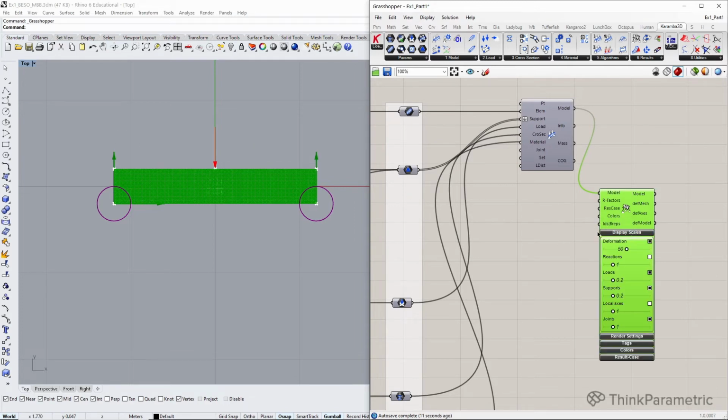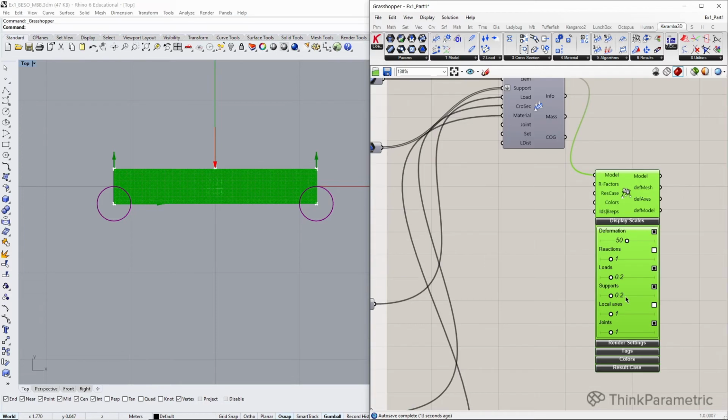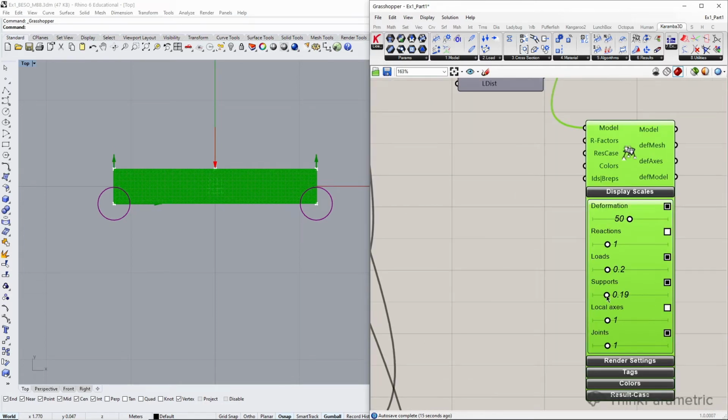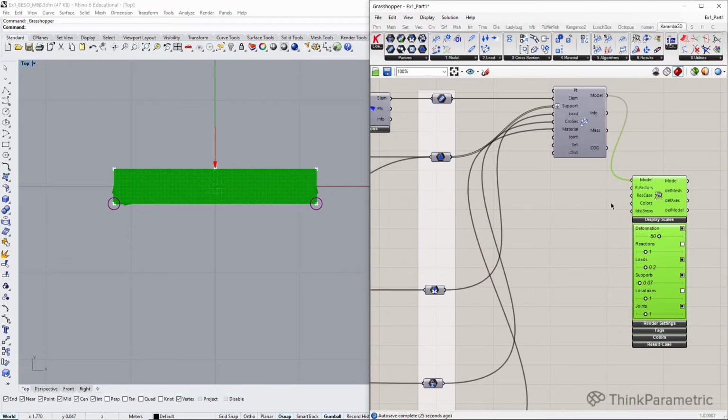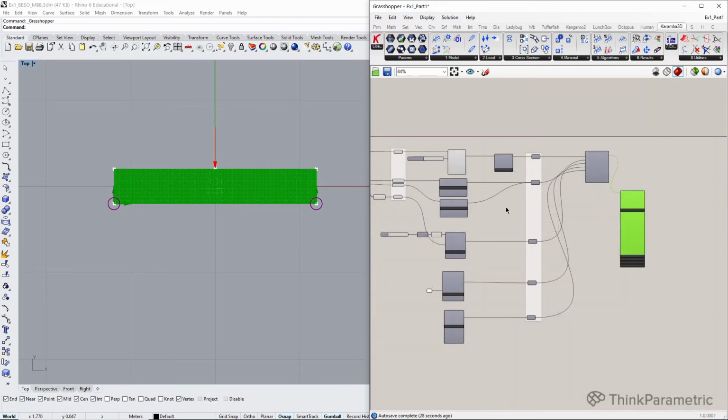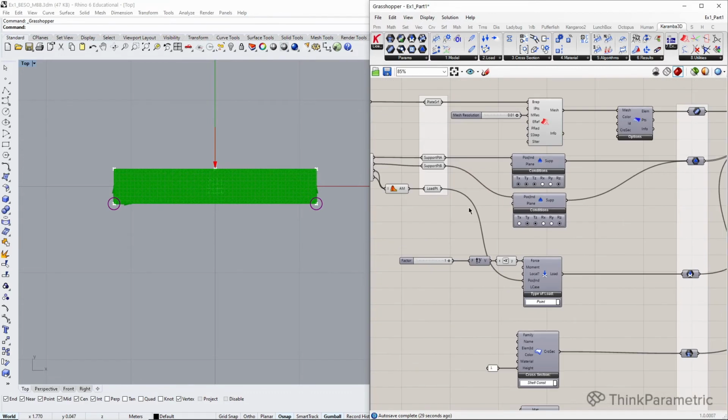As you see, the supports look pretty big, so I can just go here and check the scale of our display to make them a bit smaller so they look more realistic. This looks quite fine for now, but there is one issue, that we didn't select these points out of our initial mesh that we created. These points are just points from the initial geometry.